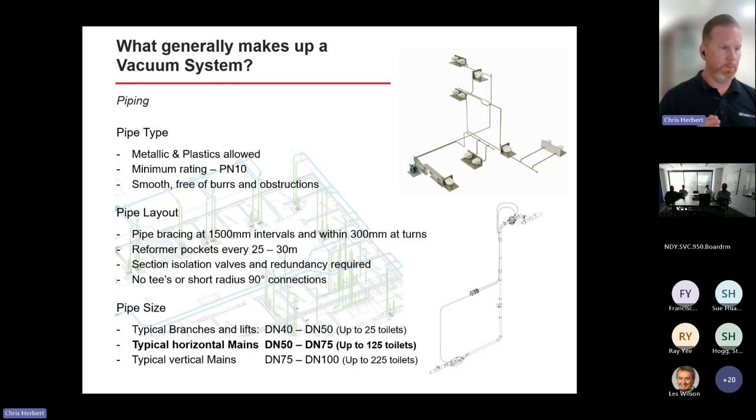So with a 1% fall on pipework at 300 mil every 30 meters, we can do 300 meters of horizontal run. This gives you really lots of flexibility in terms of placement of hydraulic services within your floor plate, but it also gives you 100% hydraulic coverage across a floor plate for your customer. So you can bring water in and bring waste out in the exact same route across quite a large area.